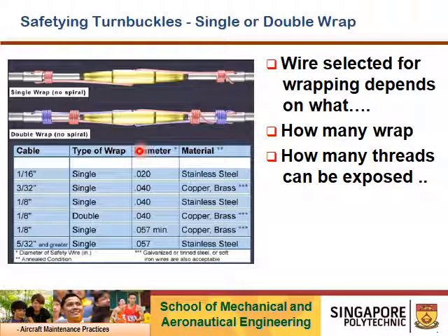Either you can carry out lock wiring, in this case as shown here, or you can install a clip. Okay, there's a turnbuckle clip. So what is the difference? Both work the same to prevent the barrel from rotating uncommanded. But the installation will be slightly different. Lock wiring is a bit tedious and more time consuming, while a clip is fast and easy. So during the practical, we will let you experience both and you will see the differences.